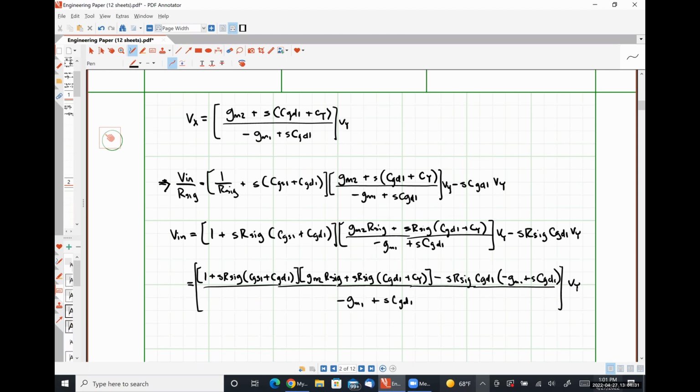All right, so we can see from here where our transfer function is coming from. Can we at least agree on that part? Okay. Are you humoring me? Probably. Okay. So all we're looking for in this part is to get a relationship between Vy and Vn. So Vn is equal to all this crap multiplied by Vy. So Vy over Vn is literally just flipping this fraction upside down. So we have a zero and then 2 poles.